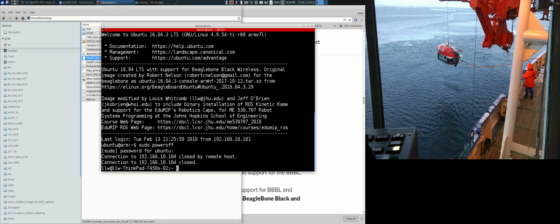So I'm going to shut this thing down, and that's not the one I wanted to shut down. I'm going to shut down this BeagleBone Blue by hitting the power button, if I can read it. It's going to go through its shutdown sequence, and it'll have just one light left, so it's shut down. And I'm going to pop out the microSD card.